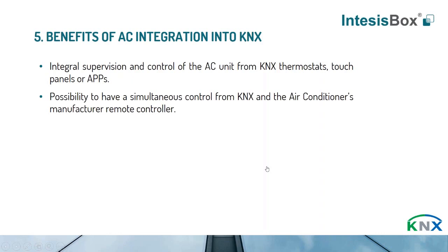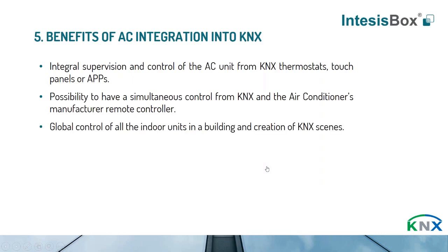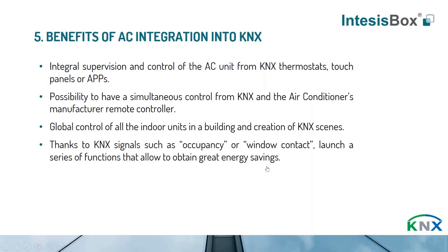Also, there is the possibility to have simultaneous control from KNX and the air conditioner manufacturer's remote control. You can also have from KNX a global control of all the indoor units, and you can create KNX scenes. Also, thanks to KNX signals such as occupancy or window contact, you can launch a series of functions that allow you to obtain great energy savings.